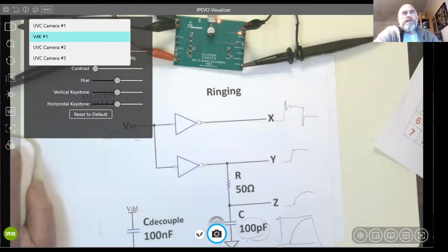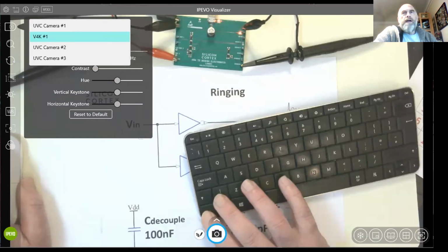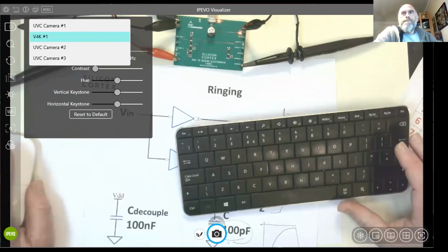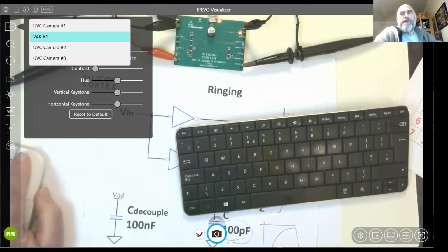And John, it's a long wire, I presume, because of the very high impedance of the ADC, that the voltage drop won't matter along the wire because there's basically no current. So all the logic will be in one box in the garage. The only thing at the other end of the wire is the vehicle's lead acid battery.